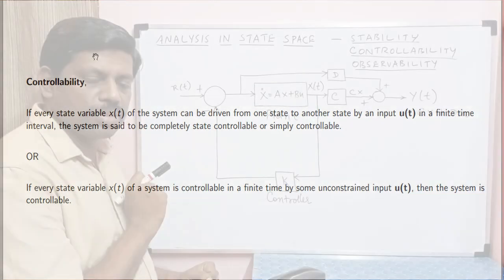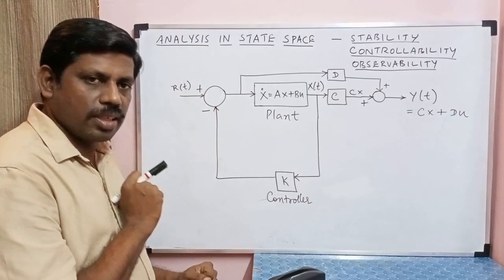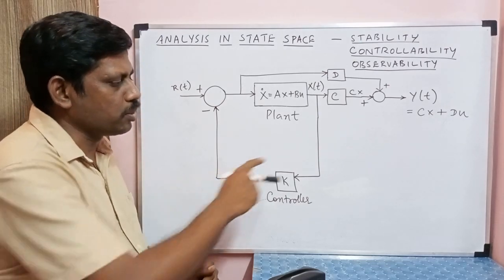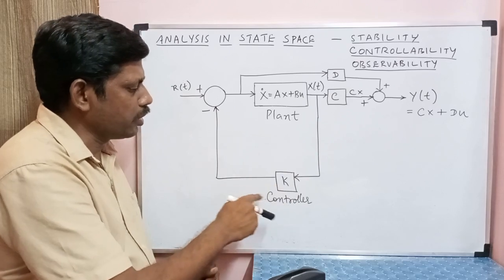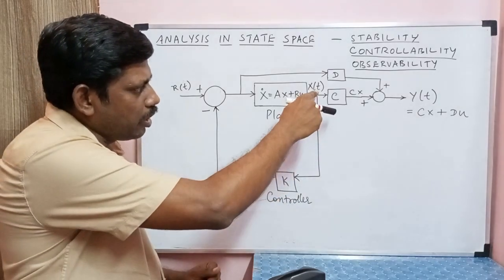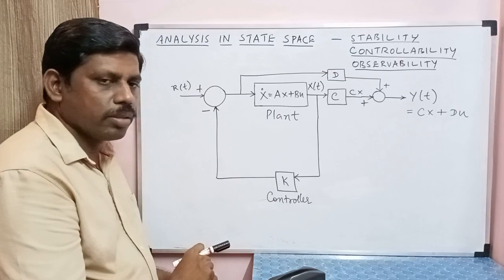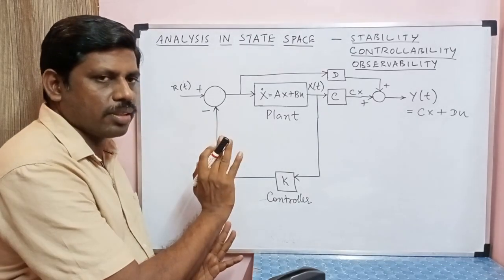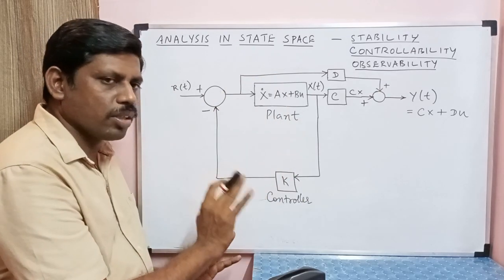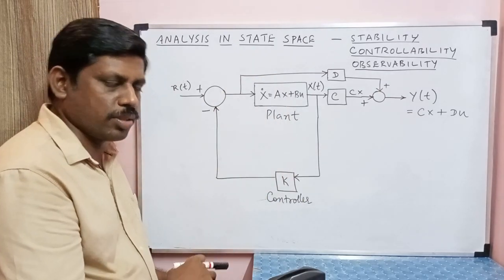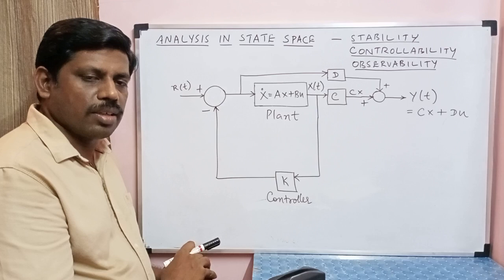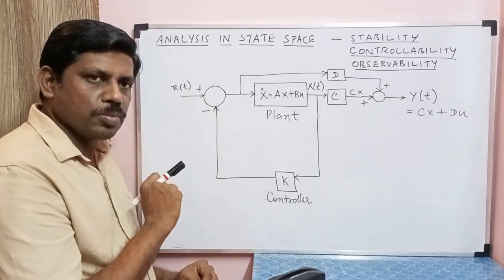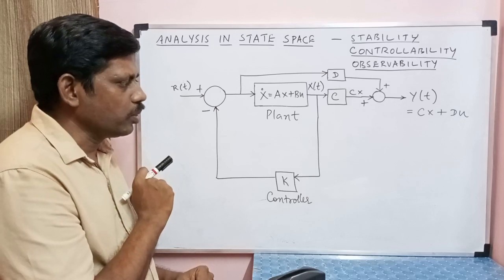The next question is whether all the state variables will be available for the state feedback. Please note, if I want to design a state feedback controller, I need to feed back all the state variables. The question is, practically, whether all these state variables will be available in the system. The answer is no. The practical problems are twofold.